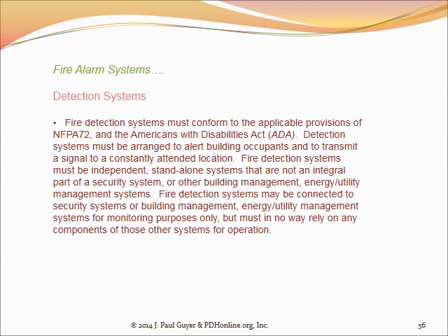The detection system must be independent and stand alone and not be part of an integral building security system. The fire detection systems may be connected to a building security system, building management system, or an EMCS system, but for monitoring purposes only, and must not rely on any of the components of those other systems for their operation.